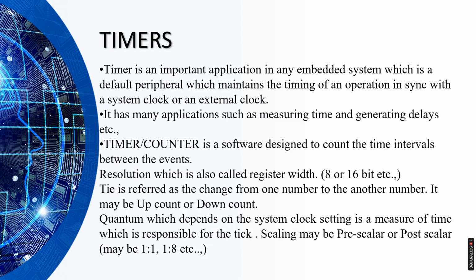Moving on, we have timers. Timer is an important application in any embedded system, which is a default peripheral which maintains the timing of an operation in sync with a system clock or an external clock. It makes sure that there is some time sync which the user can relate with the system, and the system can make sure of the unit of time for how long it must operate. It has many applications such as measuring time, generating delays, latencies, etc. Timer, which is also known as counter, is designed to count the time intervals between events.